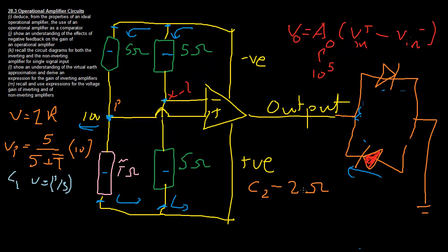So if it's at 2 ohms, when it's at 25 degrees, let's think about what the ratio is. The ratio will be 5 over 5 plus 2, and that's just 5 over 7. If we want to take that numerically, 5 over 7 is about 0.714. I just did that on my calculator.